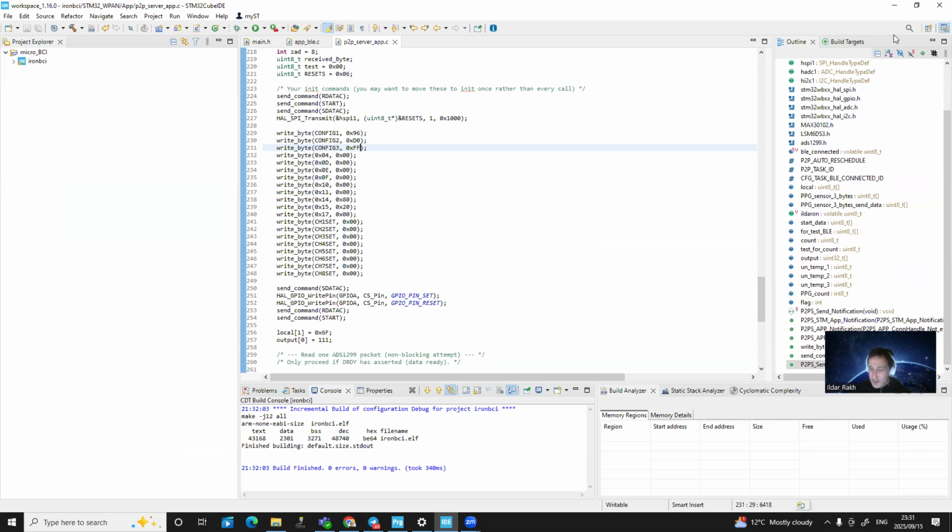to launch your device and start measuring biodata. But first, it's necessary to disconnect the device from the power supply. In my case, I use this type of power battery. So you need to connect MicroBCI with Nucleo directly to the power board and connect electrodes. And you'll already have the opportunity to measure EEG.